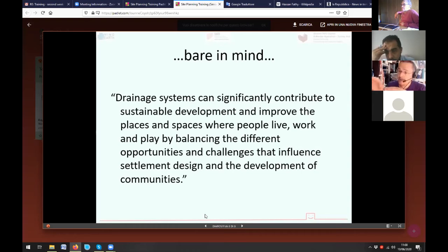And then we go back again to the survey that you have. Of course, we can rely on satellite imaging, but if you can combine it with an accurate total station survey or a drone survey, this is the best option that you have. And also keep in mind, just to interrupt you, if you do any construction work in terms of mitigation for flooding, you need to have a precise survey. You cannot rely on a digital terrain model from the internet. Of course, as soon as you do a drainage or a retaining wall, you need to be precise. You agree with me, right? Yes, I do agree.